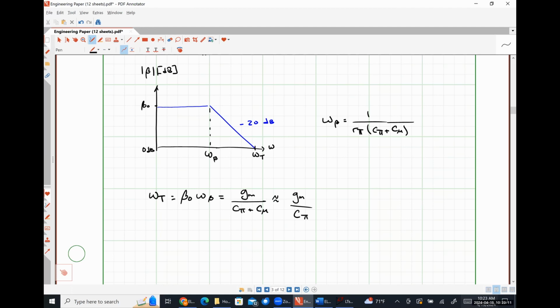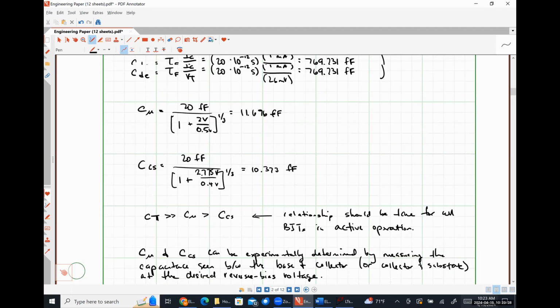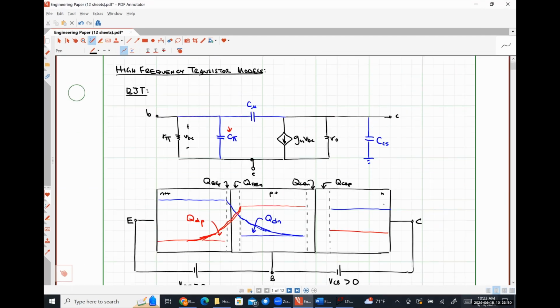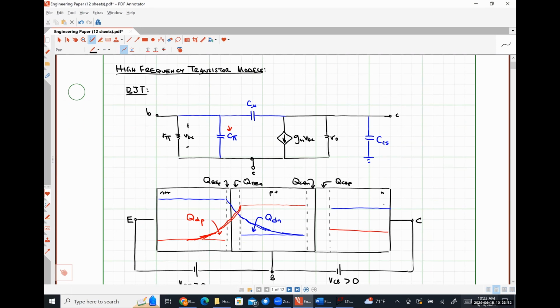So that's a very good question, right? If we were talking about our DC biasing and all of that kind of stuff, literally all of our inputs are purely DC, right? So all of those capacitances, let me go back to our model here, would look like open circuits, and we would literally just have the exact small signal model that we're used to dealing with at DC. So these are telling us how it's going to behave when we excite our circuit at high frequencies.